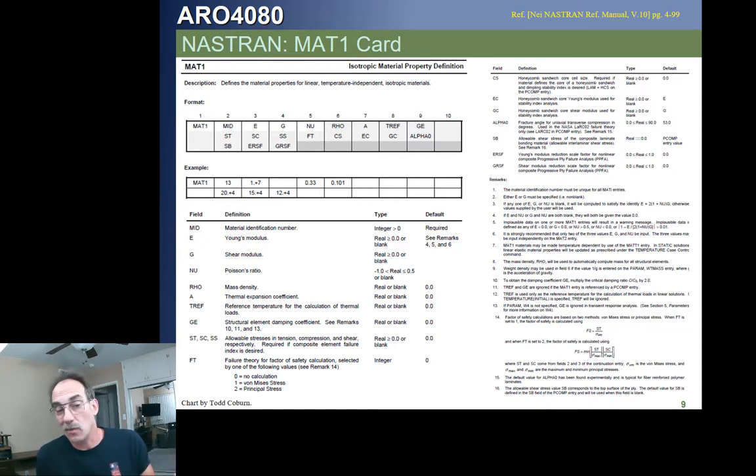We're usually going to just number them from 1 to however many materials. You're then going to have the Young's modulus, the G, and the Poisson's ratio. It's bad practice to put in more than 2 of these. You put 2 of them. Any 2 will suffice. Usually E and G will be best. You can also put E and Poisson's ratio.